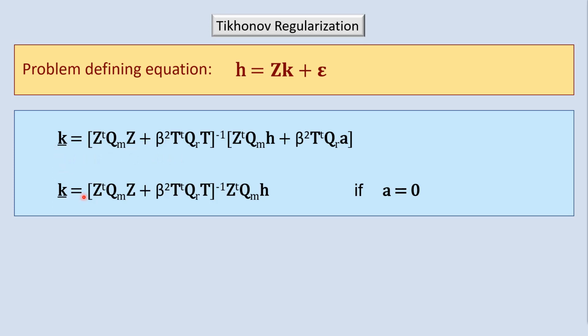These equations require that a matrix be inverted. Now, Tikhonov regularization ideally should make that matrix invertible. In practice, in difficult inversion settings, many of which arise in calibration of a groundwater model, that matrix may not be invertible or may be nearly singular and may be difficult to invert numerically.